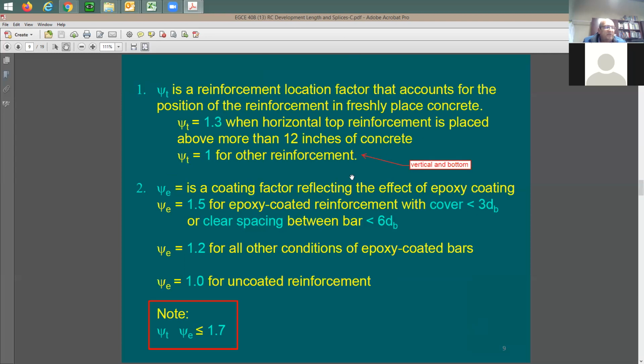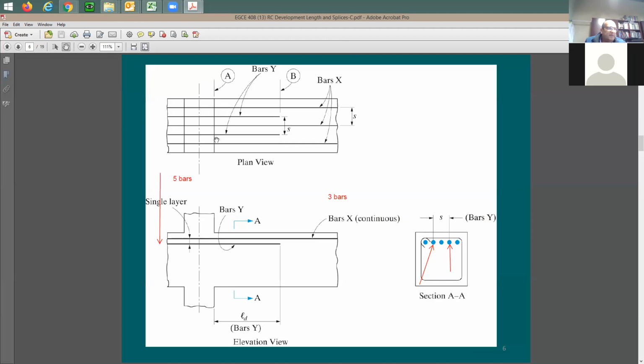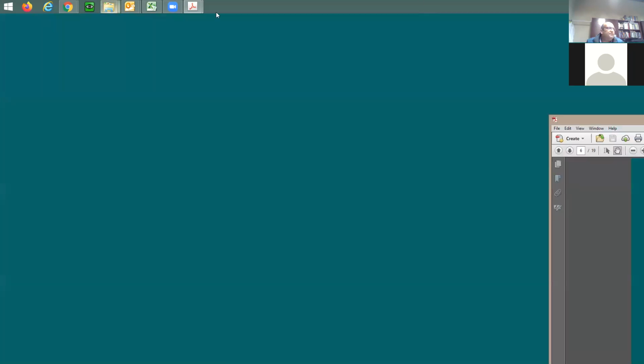So this straight development length is good, I mean, for a certain distance or certain length, you should be able to transfer the force from the rebar to the surrounding concrete. The problem is going to happen at certain locations, and this is where we're going to start today's lecture. Slide set 14.